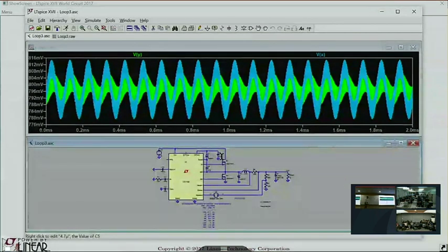Now, you get some use out of linear analysis of nonlinear systems. Say you want to make a power audio amplifier. Before you apply a signal to it, the thing is just in equilibrium at a bias point. It acts as a linear circuit at that bias point, and you can do frequency domain analysis, and there would be some correctness to it.